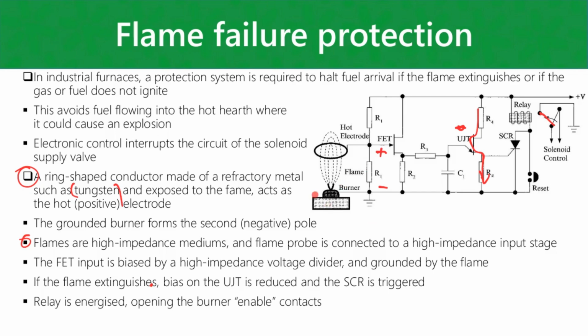Because what you don't want is fuel pooling in your furnace, and then when the burner is ignited again, you're going to get a massive explosion in your furnace from fuel just hanging around there. So that is pretty much what this circuit needs to prevent.